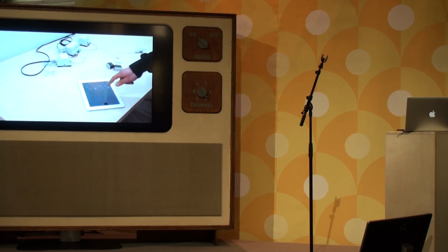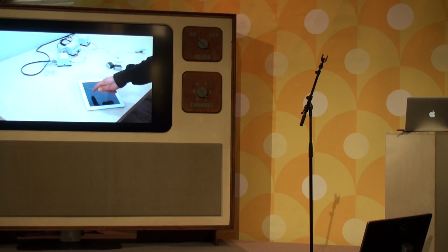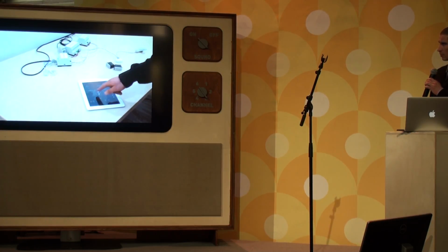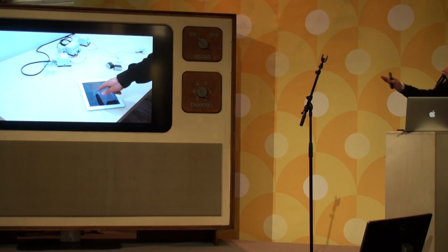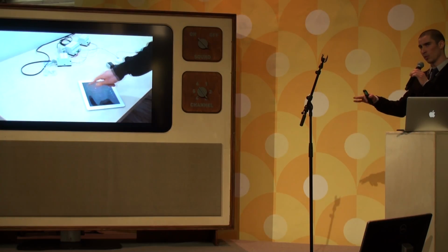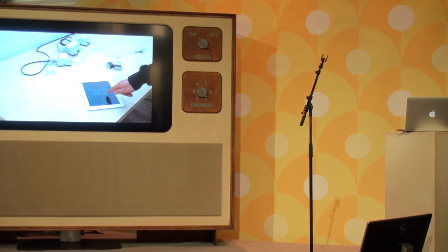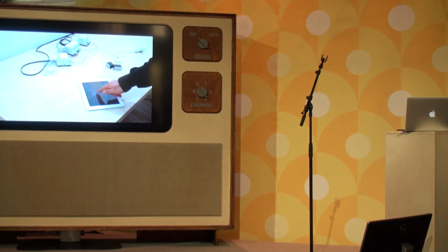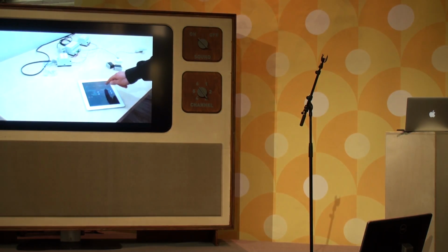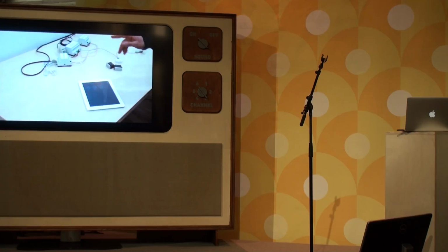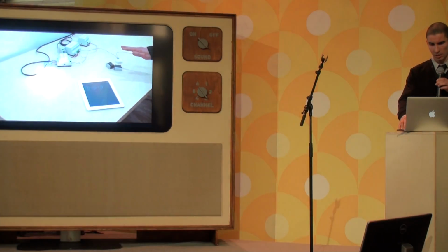We go to automatization, auto, and we are concerned with turning on and turning off the light. Right now, it's going to be turned on at the motion level of 30%. So you can change the time when the certain light should react to the sensor signal. The turn off mode: now it's at 30 minutes, which is a very long time. We want it at 3 seconds. Okay, and then we press save. So now, what's going to happen is... Okay, so it did work.